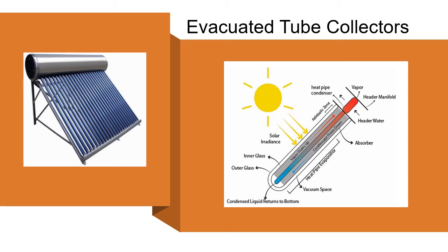In this cycle, solar heat evaporates the liquid, and the vapor travels to the heat sink region where it transfers its thermal energy to the heat transfer fluid and condenses in the process. The condensed fluid then returns back to the bottom of the tube, and the process is repeated. The heat pipes are generally treated with a dark-colored paint to better absorb solar radiation.